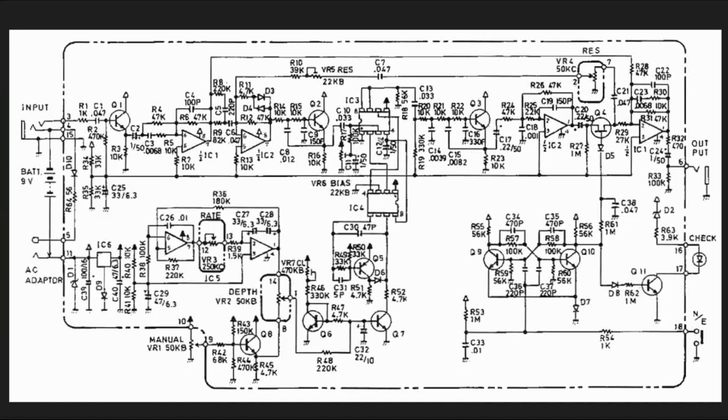So then we go into our BBD device. This does the delay for us. Now, if we're just coming in and doing a delay, how is this circuit any different from a chorus? Well, the real difference between a flanger and a chorus is in the amount of delay time that you have. They are both using a modulated delay line, but how long that delay is that you're modulating is going to determine whether or not you're getting flanging or if you're getting chorus. Okay, that's the first difference. There's a second difference we'll talk about in a little bit.